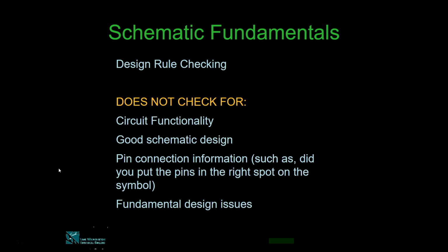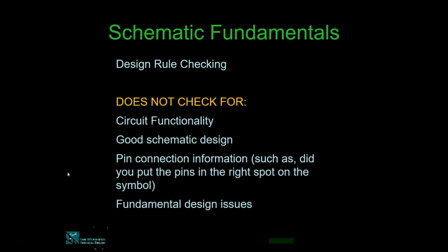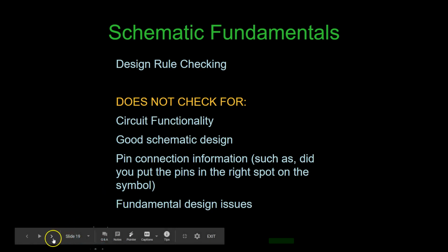It does not check for good schematic design. Pin connection information, such as did you put the pins in the right spot on the symbol? Fundamental design issues, all these things it does not check. So you have to make sure when you design the circuit in KiCad that you keep all these points in mind.